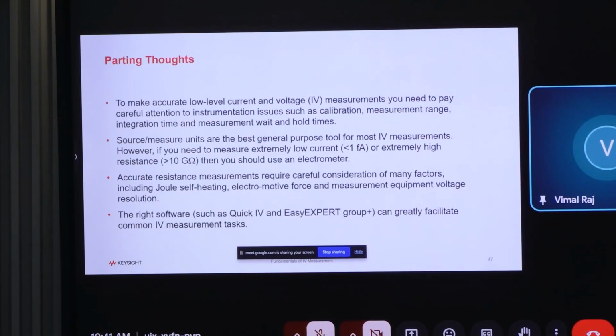If you are achieving less than a nanoampere and you want to measure high resistance, automatically your current will be very, very small in the high resistance measurement, and the current fluctuation will be very significant when measured. If you follow these steps, you can easily achieve the measurement. And third will be the temperature effect in the measurement. Your sample, if it is continuously applying current, will get overheated. Because of that, your resistance value will also change, and interferences, how we can avoid the external interferences.